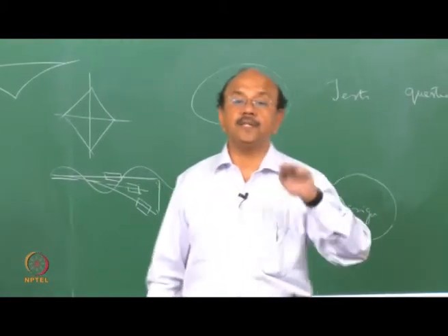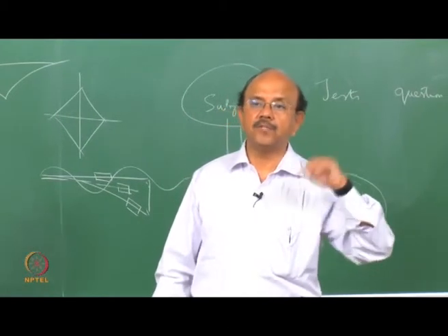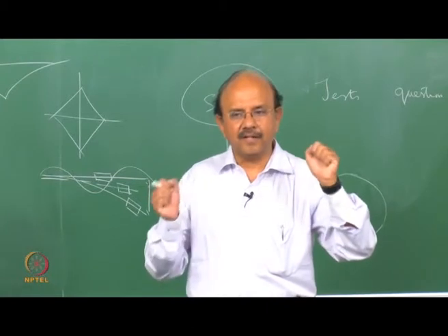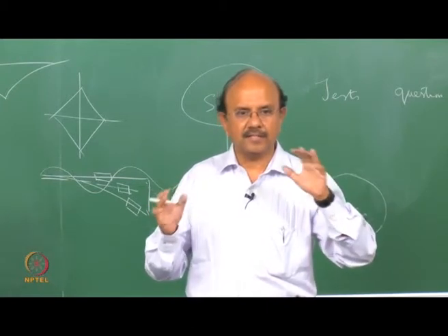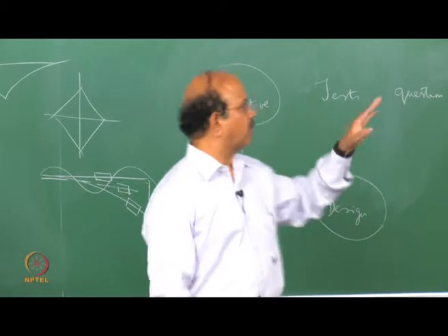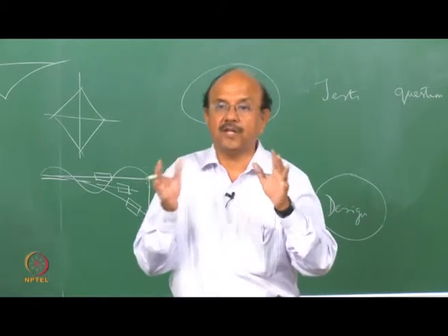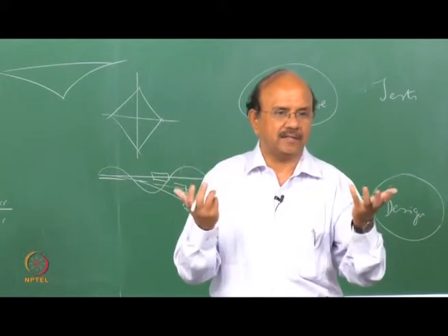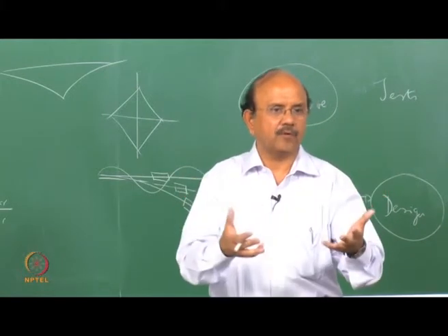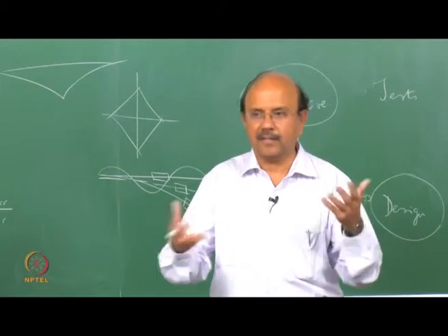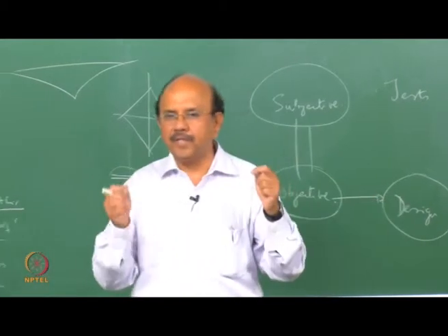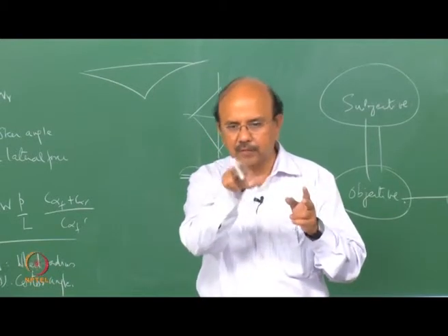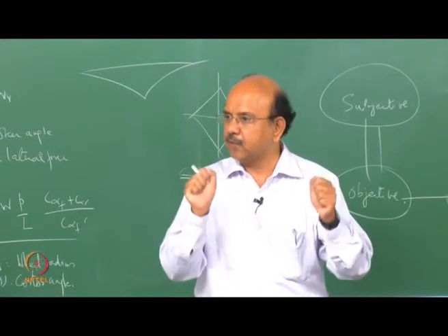See, one of the major things in the driver's field subjective is they look at that nose angle and they look at the feel in that steering. See, these are very, very important. Though we talk about wander and other things, actually the driver won't allow it to wander. They will keep on correcting the steering. I'm talking about testing, and even when you drive, there can be a wander, and what does the driver do? He keeps on adjusting. So he knows the nose of the vehicle, what is its attitude, and he keeps on correcting it.